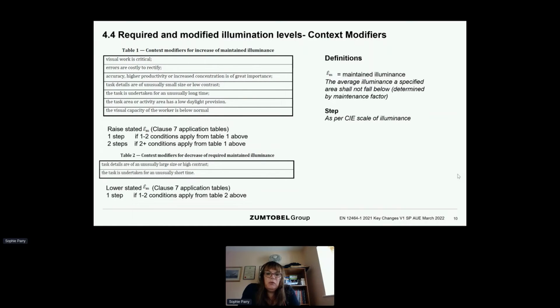So the maintained illuminance is the illuminance you should be delivering on the day of that first service due. That means that until you get to that point for several years, you may be actually overlighting the space for the value you want, as the illumination depreciation finally glides down to that point where you get to the first service. So that is another subject again of overlighting to satisfy maintenance factors and the energy actually wasted in those intervening months or years.